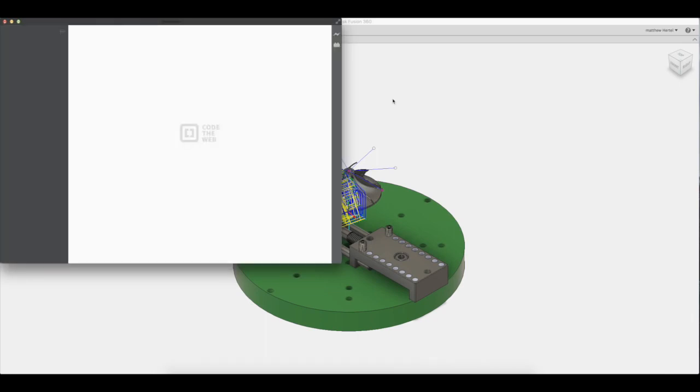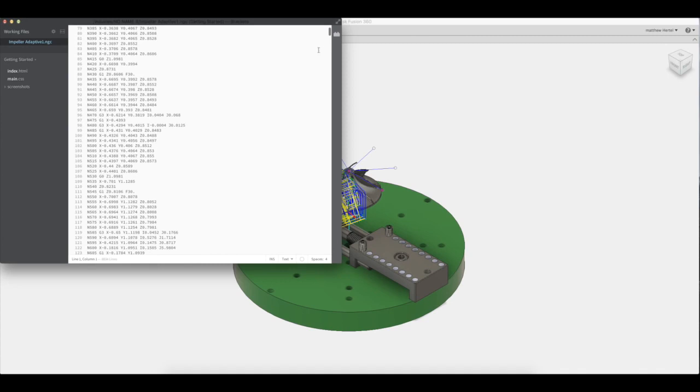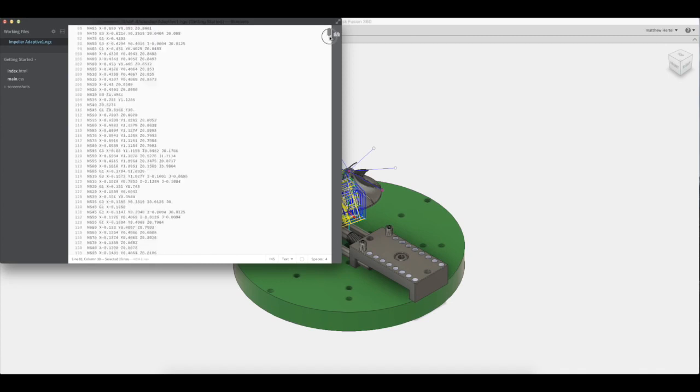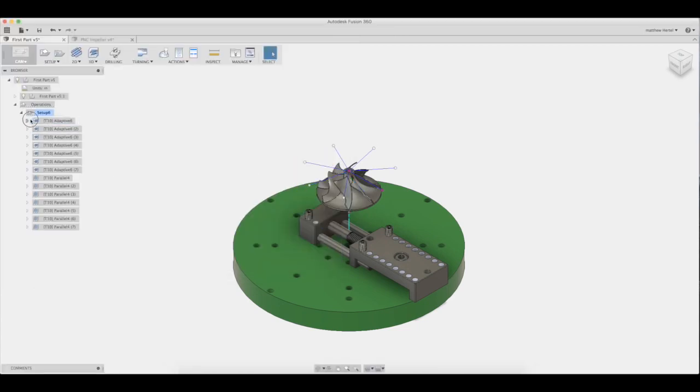Once you've saved your toolpath, Fusion will load the program brackets. This allows you to make small edits within the program. We don't need to make any edits, so we can go ahead and close the program. Large programs take longer to load with the Pocket NC. To check each individual toolpath for its size, you can simply click the arrow next to the toolpath.